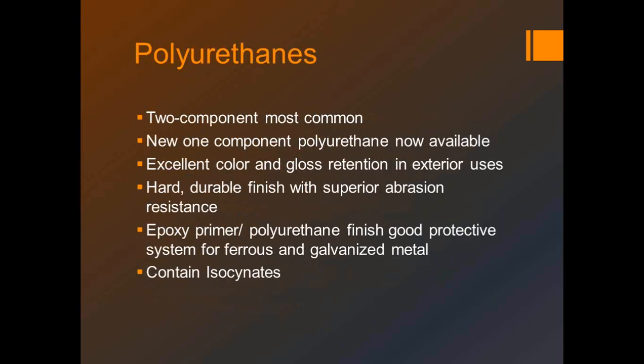Polyurethanes. The thing that really impressed me about polyurethanes, I remember about 30 years ago actually, when I first found out about them, the Tnemec salesman came by and he had 2 coupons of metal. They were identical color, and one was a really good acrylic enamel, the other one was polyurethane. He laid them side by side and took steel wool and ran back and forth. The alkyd scratched like crazy, and the polyurethane was essentially untouched. Yeah, that's one of the benefits of polyurethanes.